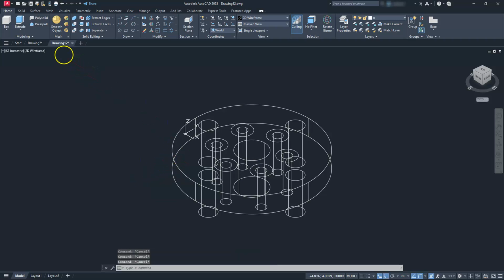Okay. Next, I'm going to go back to the extrude command, and this might be a little hard to see. And it's going to be hard to select if I put it in any other visuals, but I'm going to try to select them here. And hopefully you can see the ones that I'm selecting. So I want to select all of these circles here. So it should be 6 of them total. I'm looking down here on my command line, and I do have 6.